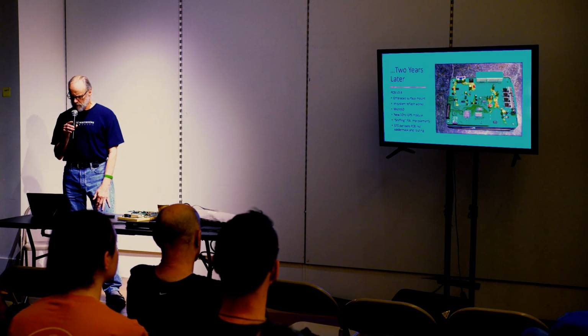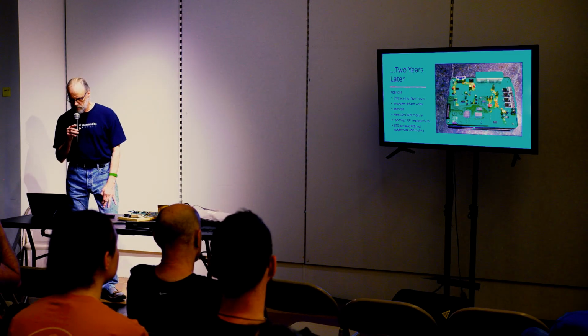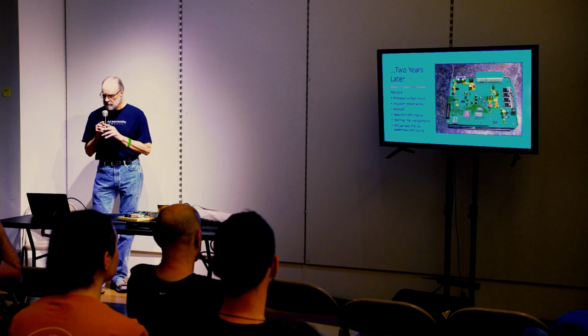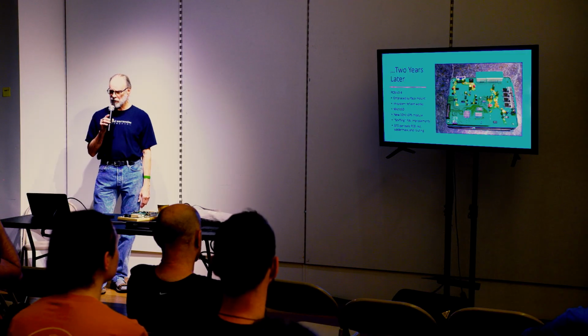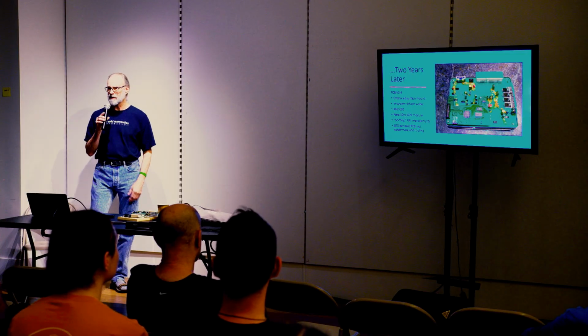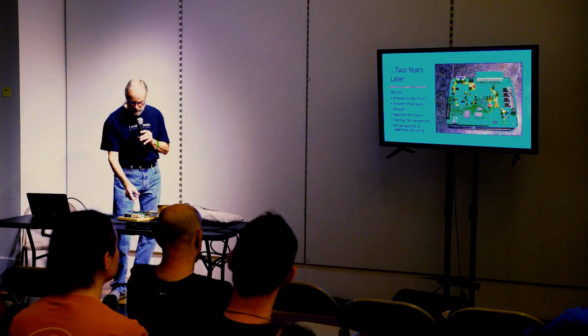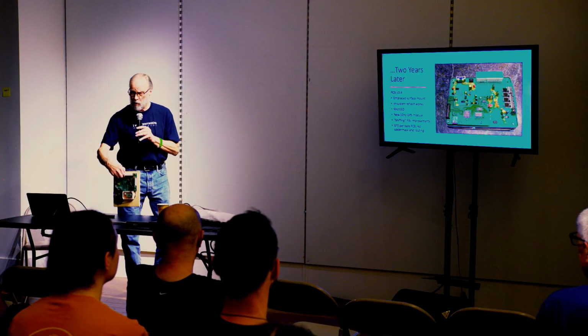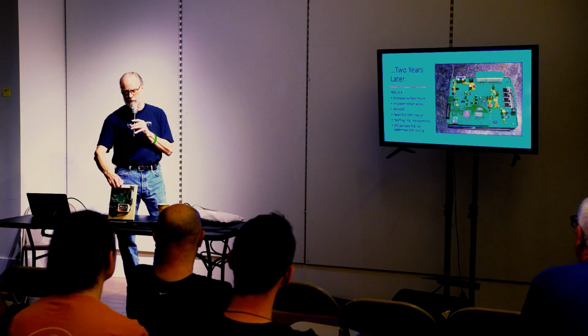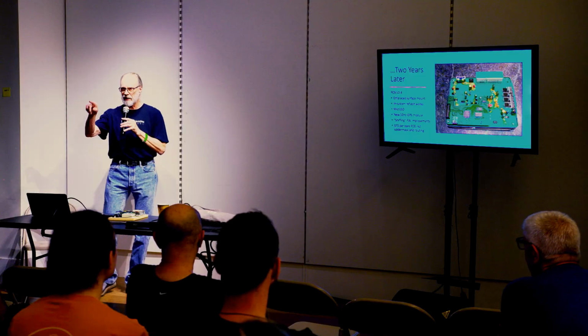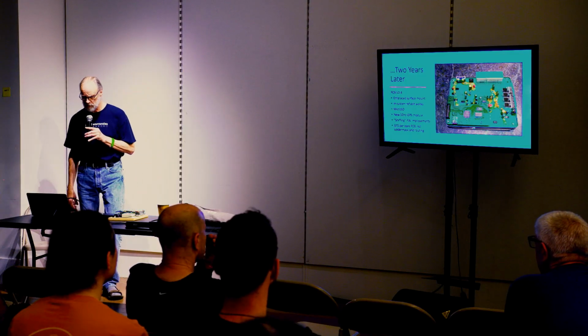I think I went through about 3 different GPS modules, and I finally paid money so that I could have solder mask and stuff like that, PC routing. That was important because you can see here, there are components that stick up on the bottom, and so I had to have a pretty complicated routing path to avoid those components.